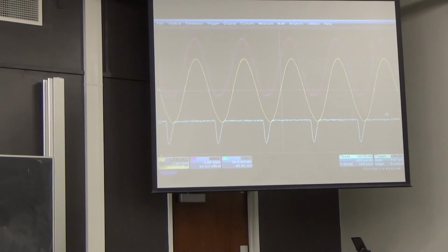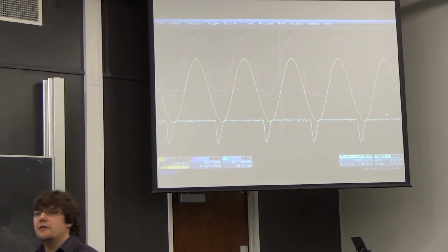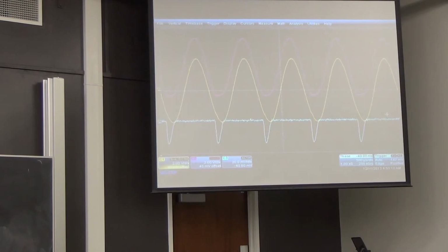Thanks. So, we've now got the situation where the input, which is in yellow, and the output voltage, which is in red, have the same ground reference. So we can compare them just by looking. We don't have to worry too much about what's above and below the line. And we can see that it is shifted up, because in the case of the magenta line, minus 0.7 volts is where it's a bit flattened on the lowest part of the cycle. And in the case of the yellow line, that's also where minus 0.7 volts is. And in this region we have the diode conduction.